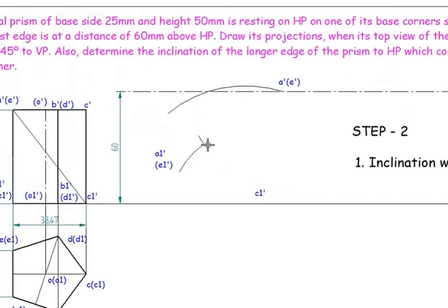After cutting an arc, I'm going to join it from this point to this point and this point to this point. When you're drawing it, make sure that this is equal to 90 degrees, because the lateral edge with respect to the base is exactly perpendicular, so it should be equal to 90 degrees.